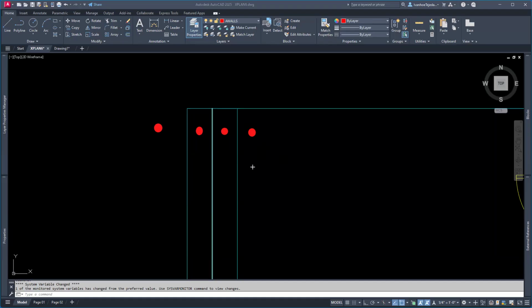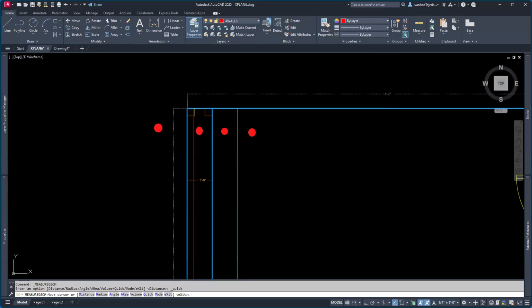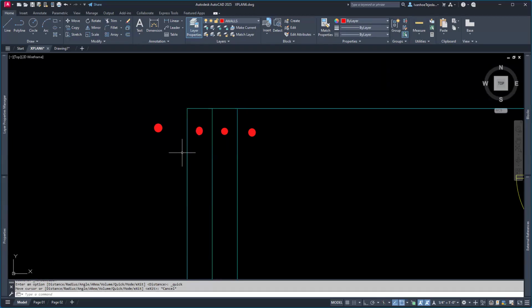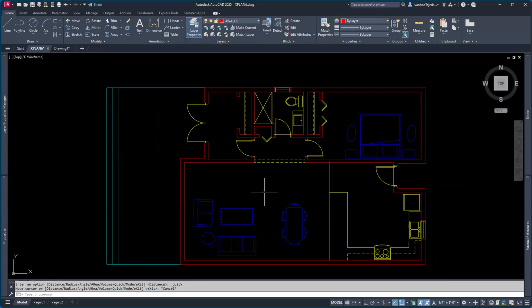This is how it's represented in plan view for the stairs. So this line here represents a riser. This line here also a riser, and this one as well. And between the risers, we have what are called the treads. That's what we step on. And those treads typically are 12 inches or so. I'll do a quick measure here and show you. Yeah, I made it 1 foot. So yeah, make it 1 foot, you'll be okay. All right, that's just on a side note. Let me get back to the drawing here and let's chat.